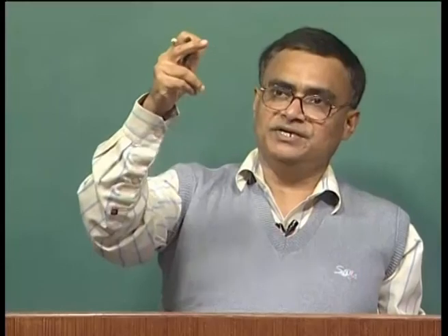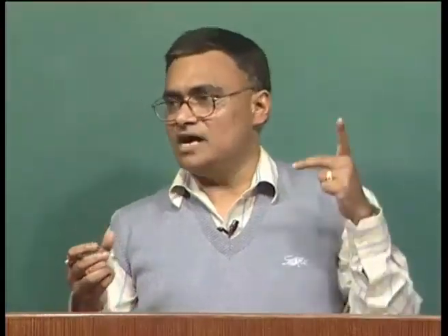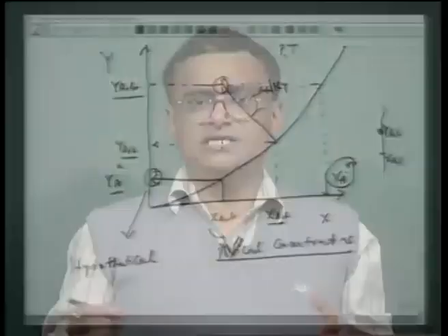So we defined two more concentrations, as if given gas phase concentrations, if the entire concentration is brought to the interface, what would be XA star? Or if we have XAB here, bring the entire XAB to the interface, what would be YA star? So YA star and XA star, these two are the hypothetical concentrations. Okay, but nonetheless we will define a quantity which we call overall mass transfer coefficients, which should be very handy in the design calculations. Instead of working on the individual mass transfer coefficients, generally we prefer to work on overall mass transfer coefficients. Okay,